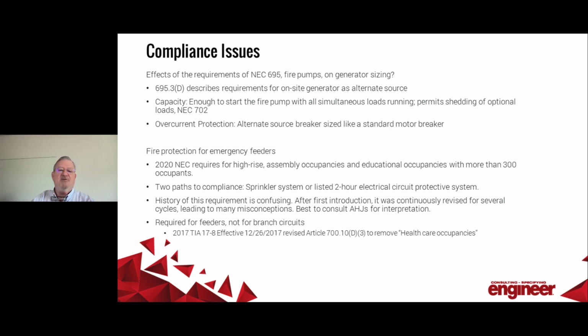The requirements for fire pump protection of emergency feeders, now I'm talking about fire protection for emergency feeders, come from NEC 700.10(D) for high-rise buildings, large assembly, and large educational occupancies. Circuits have to be protected in one of 5 ways. They have to be protected by automatic fire suppression, a listed electrical circuit protective system. They have to be fire-resistive cable, or they can be protected by a couple of structural methods.